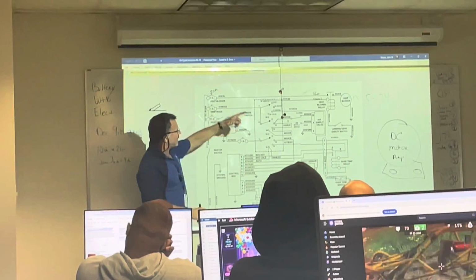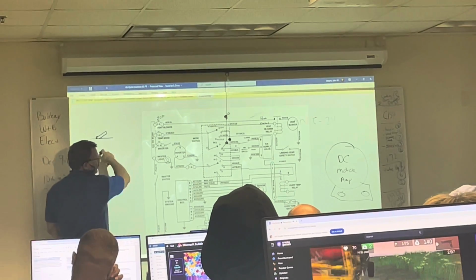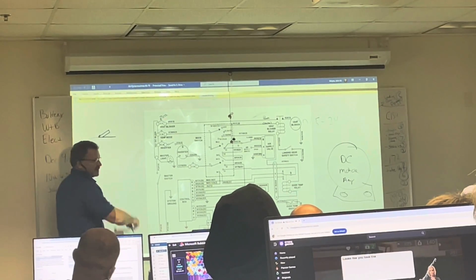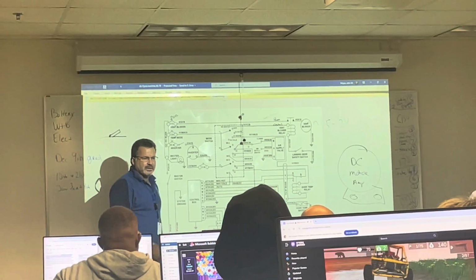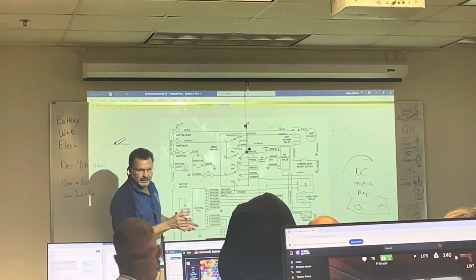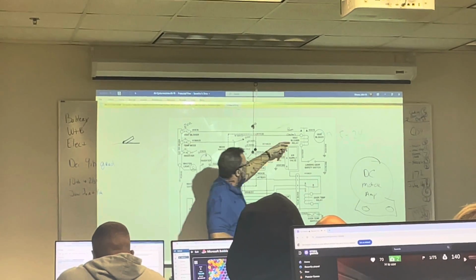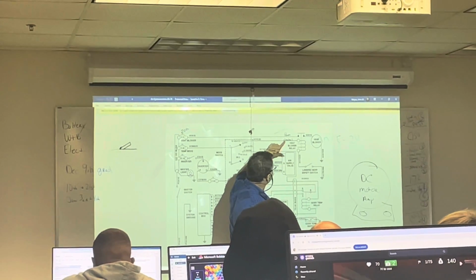Because if I did not have that electronic switch be my relay, and I wanted to go switch to motor, that's got to be a much bigger switch. Because what is a switch, what is a circuit breaker? Circuit completers. Yes. They're not considered a load, they complete the circuit. But because we've incorporated an electronic switch, we have a control circuit.